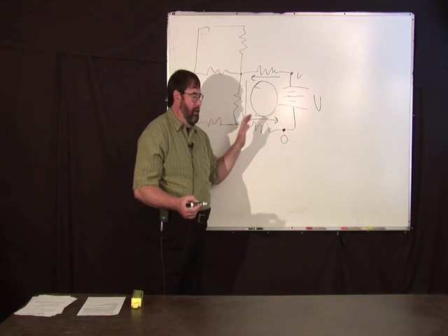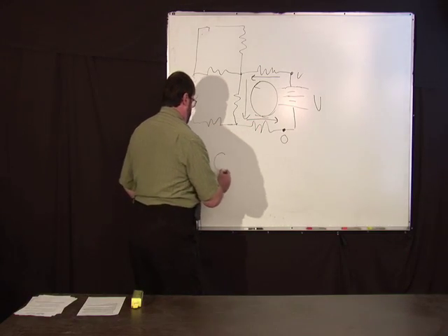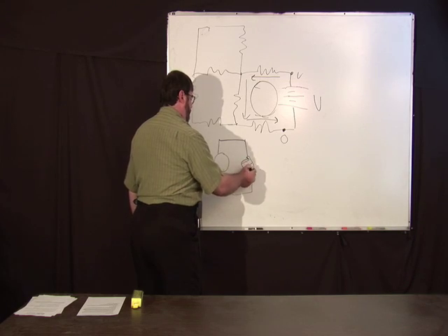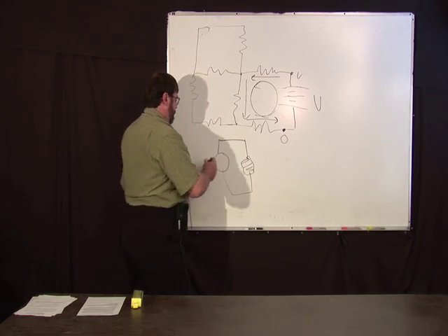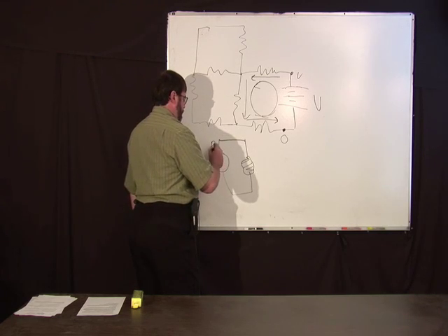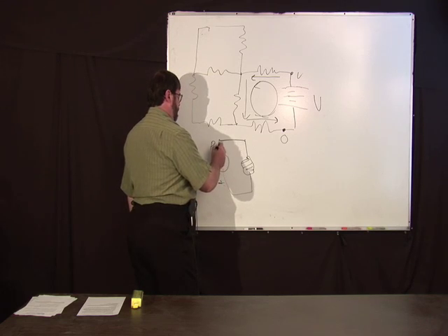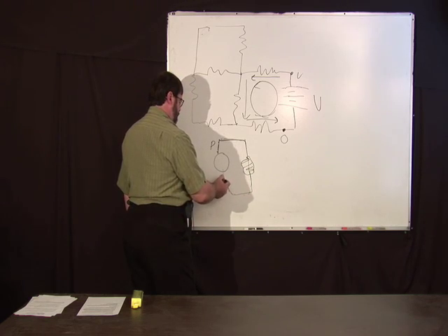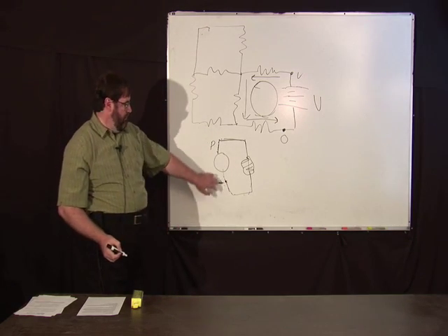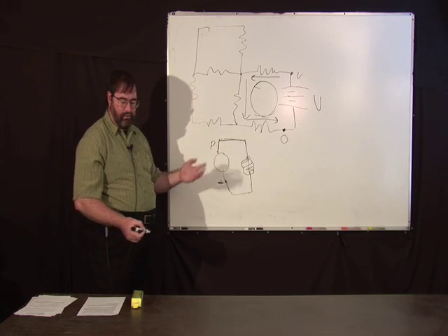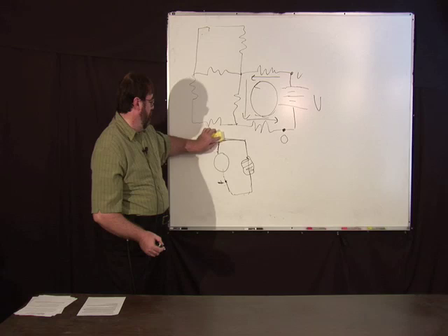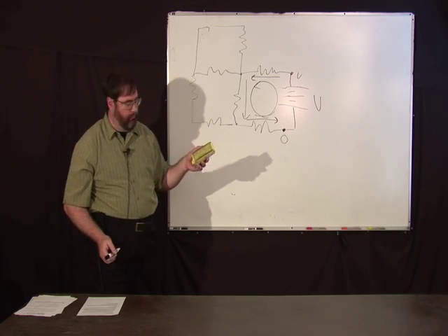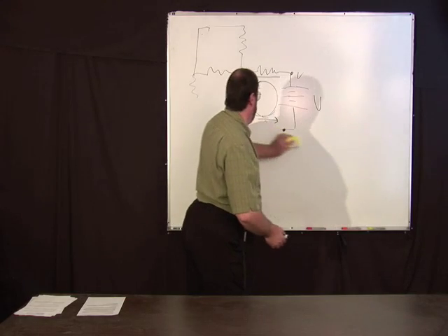Because it's the same thing as with the water analogy. You have pumps that circulate water, and it might have something in the way, like a thing filled with sand. And you have something called pressure. The pressure's higher here and lower here, but if you start here and go around, the pressure will drop when you go through there. And eventually, if you start at one point and come back to it, pressure has to be the same if it has any meaning. There's the same sort of law in the case of water analogies. So we've got two laws now, Kirchhoff's current law and Kirchhoff's voltage law.